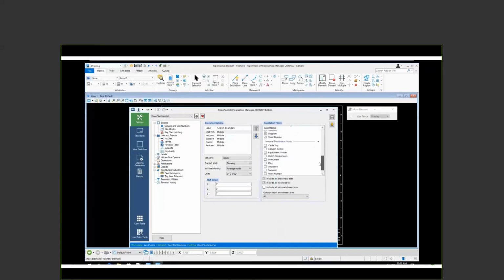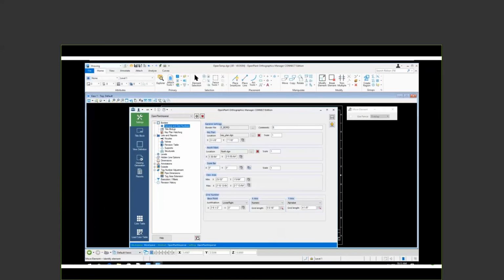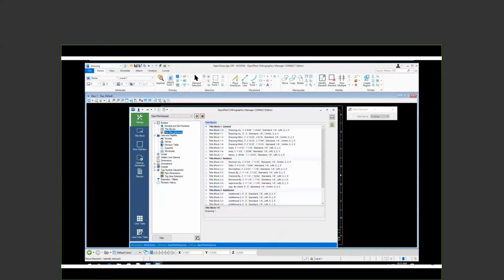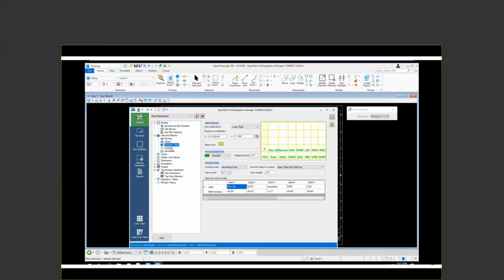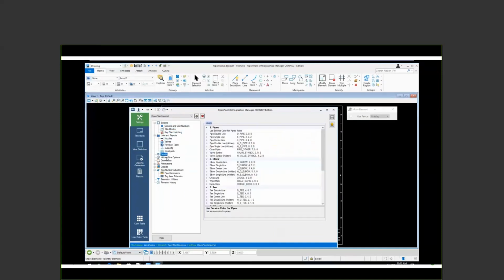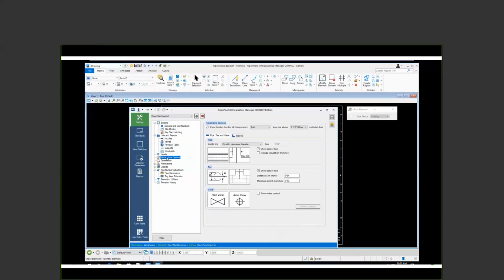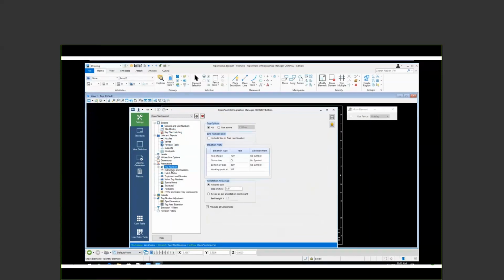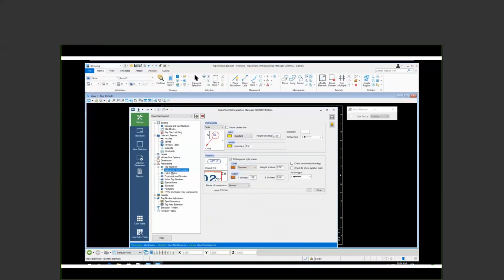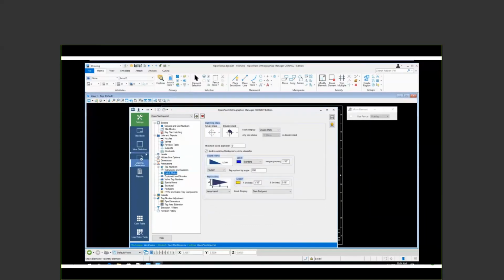And you can simply check those on and off, and those will either appear or disappear. You can get in all these other settings in here for key plan setups and nozzle reports and valve reports and revision labels and dimension and hidden line outputs and annotations. You can make piping go single line, for example, over or under a certain size. So there's a whole bunch of settings in here to predefine, and once all these are set up, you can